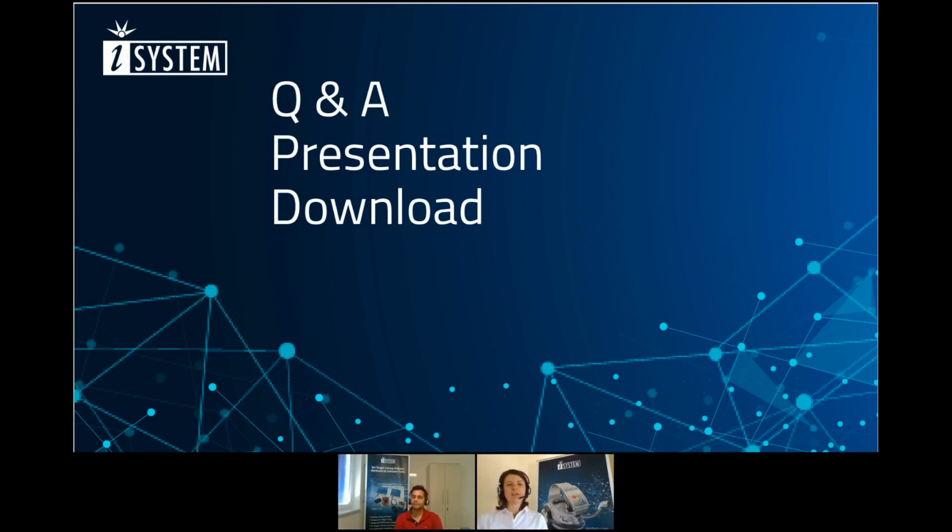I also would like to come again to the demonstration of the printf feature. When I think back to what you showed before, the ITM and DWT, the blue box needs to be equipped with a so-called trace activation key. As soon as you want to use the analyzer, you need a trace activation key. You used now for the printf feature the WinIDEA console. Does the user also need a trace activation key then?